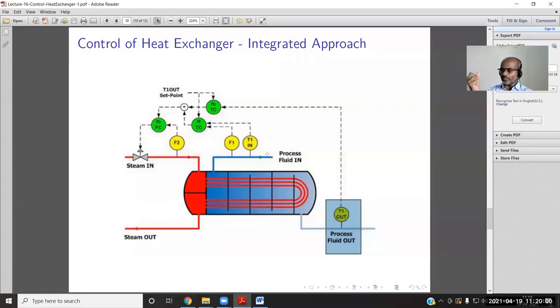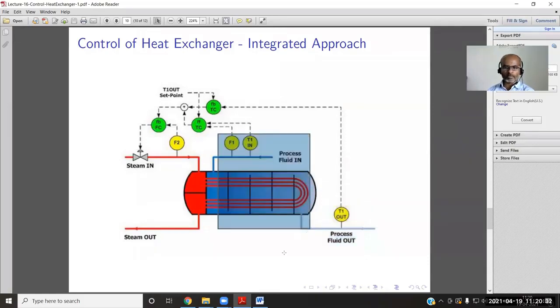Like feed forward control. You can compare this to an educated parent rearing their child, but we cannot easily match with that. At least we can match it somewhat. Feedback is a better way. Otherwise, without having any idea about the process, we can still take control. But sometimes it may be a late control. And feed forward, slightly ahead, but we need to have a very perfect model of the process.